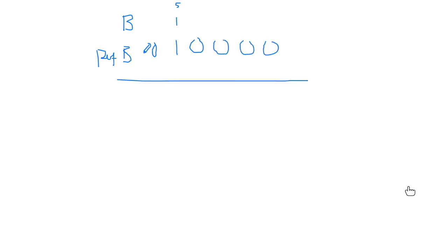So we have an OR, we pick another bit. Let's call this the reference bit, right? So we do an OR with 0, 0, and then we have a 1 on the pin we are interested in, the rest 0. And we write to the whole port.